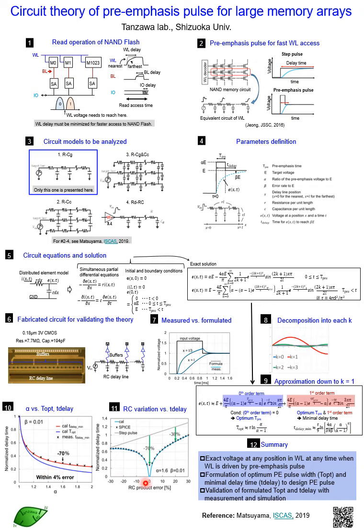So far, the RC time constant is predetermined. However, in the actual world, R and C vary. Actually, plus or minus 10% should be considered in the design. If R and C vary independently, the RC time constant must vary by plus or minus 20%.